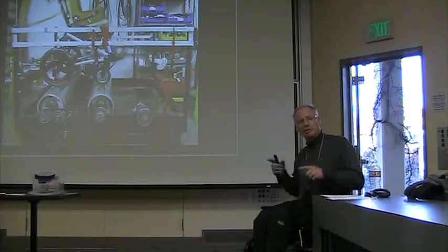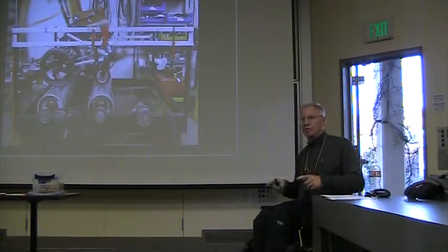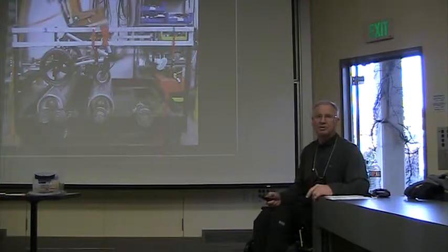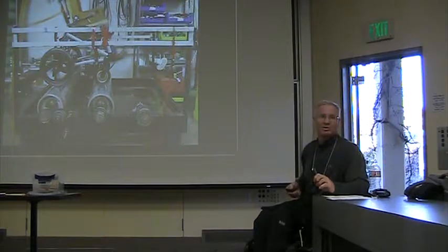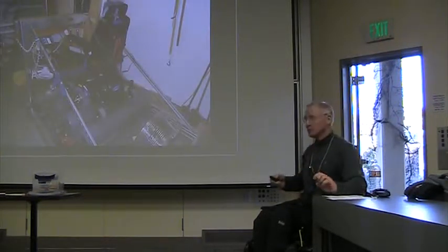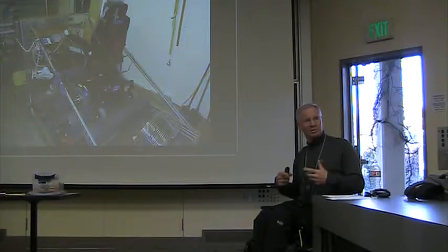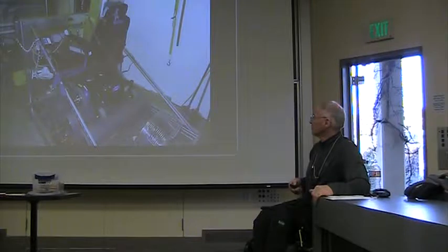Then we put it on a machine. It's a machine that's driven by a motor. The slats go around and hit the wheels and jostle the wheelchair around. It's got a very heavy test dummy inside of it. It's got to go 200,000 cycles on those drums and survive. And we also use powered wheelchairs, and the powered wheelchair actually drives the drums to test itself for the same number of cycles. And we have a drop machine.